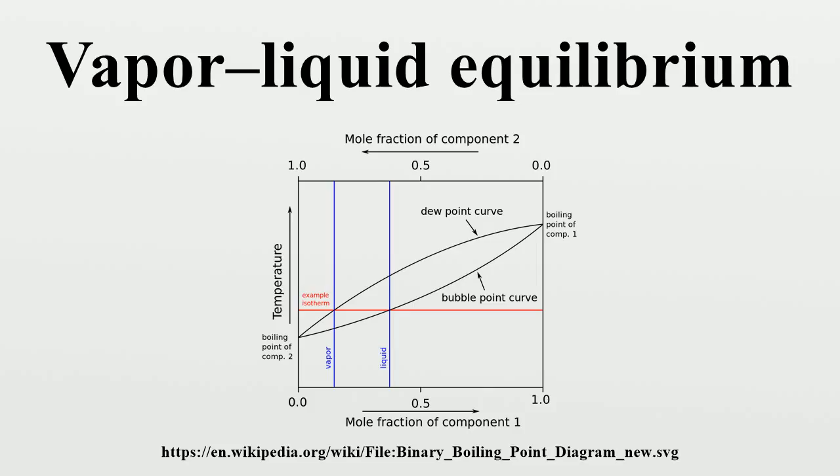For such multi-component mixtures, as well as binary mixtures, the vapor-liquid equilibrium data are represented in terms of K values defined by K_i = y_i / x_i, where y_i and x_i are the mole fractions of component i in the phases y and x respectively. For Raoult's law, and for modified Raoult's law, where gamma is the activity coefficient, p_i is the partial pressure and P is the pressure, the values of the ratio K are correlated empirically or theoretically in terms of temperature, pressure and phase compositions in the form of equations, tables or graphs such as the De Priester charts. For binary mixtures, the ratio of the K values for the two components is called the relative volatility, denoted by alpha, which is a measure of the relative ease or difficulty of separating the two components.